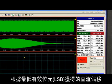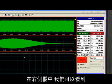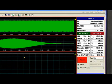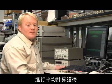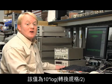The DC level shows where the DC offset is in terms of LSBs, and the noise floor is shown as the average noise floor. On the right-hand column, we can see the power in each of the harmonics relative to the amplitude of the fundamental. The noise floor is calculated by averaging all the FFT points in green. This represents the SNR of the ADC plus the processing gain of the transform, which is 10 times log of the transform size divided by 2.